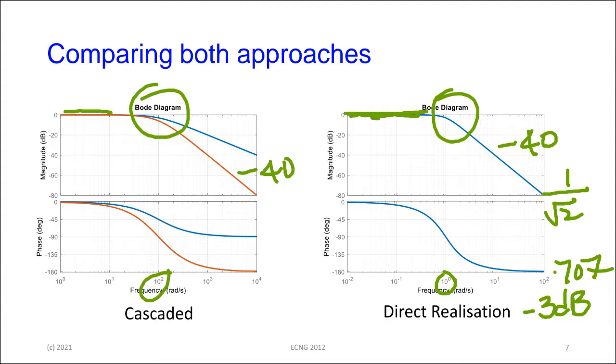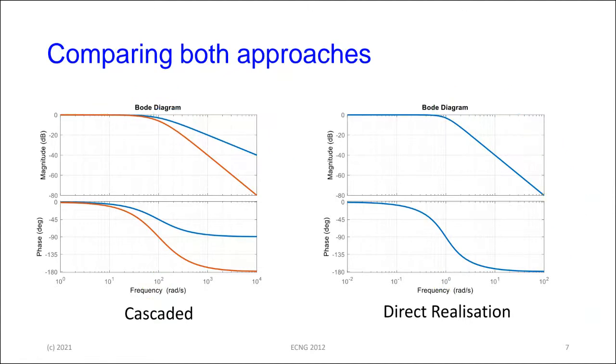Get a different color here. This point right here, that line is very fat, but that drop here is minus 3 dB. If you go across to the one that we did this morning, on the single, each single order section here is giving you minus 3 dB. But if you look at the overall behavior, this point here is actually minus 6 dB at the cutoff frequency.